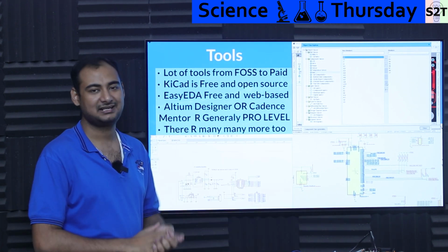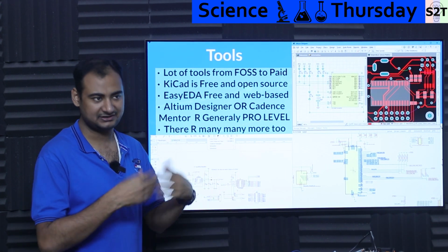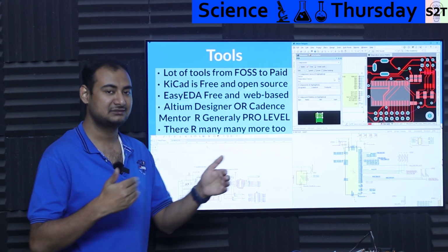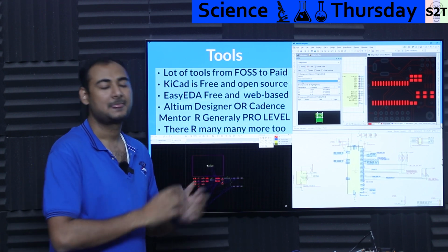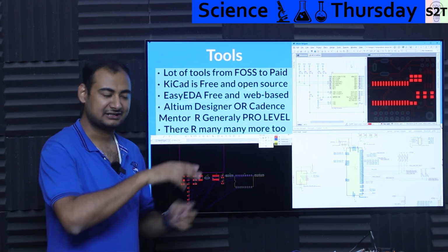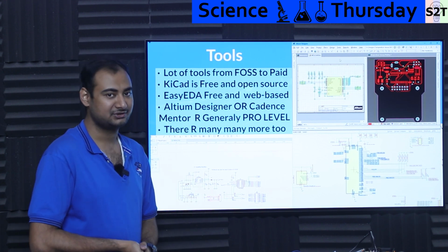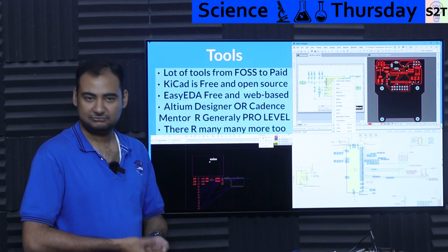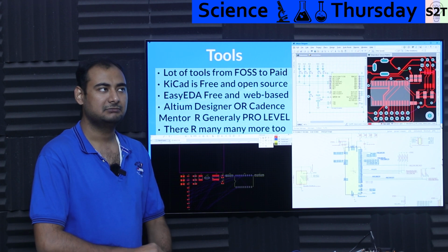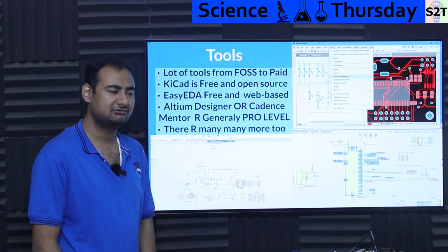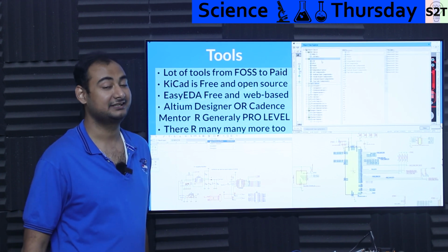So it's like taking data from design regulation rules, because again, a PCB cannot be just made out of whatever you want. There are some rules and regulations on that, from law based, basically EMF creation based, and chemical etching process limitation, meaning you cannot just have 90 degrees everywhere. It's not a good idea. So all of those go into the design documentation, design limitation, and this software will sort all those things out. There are very advanced tools nowadays. You should not hold yourself back. If you're like, hey, I'm sloppy with this sort of thing, trust me, start with this and you'll be like, damn. You will be surprised by yourself. I guarantee it.